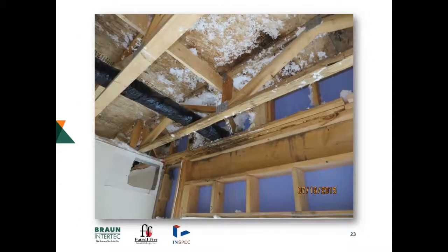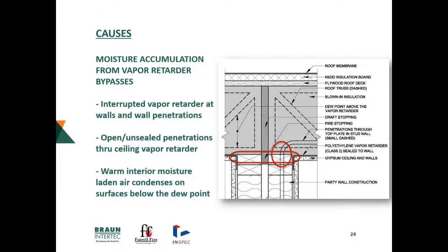Inside, we're looking at similar conditions once the ceiling sheetrock was taken off. Wall sheetrock was removed a little bit as well. Looking at those areas, we see a number of staining, wetting and mold growth areas up in that truss area. We do see some staining around a duct area that exited the exterior wall as well. So we had some poor sealant work along that condition.